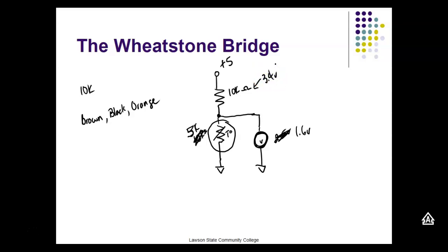So now I've got a voltage that varies with temperature, right? You understand? Now we can transmit a voltage over a piece of wire, right? And now this means something. So now I've got a quantity that I could process with something. This is why the NTCs are the most popular.